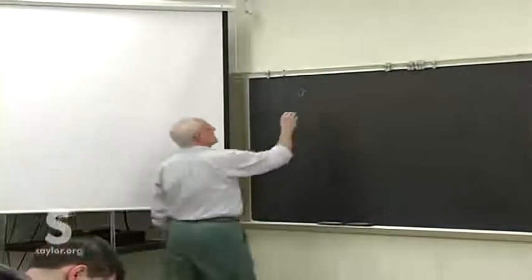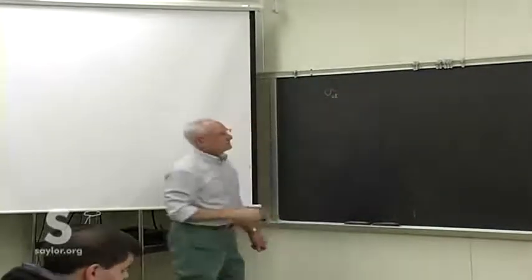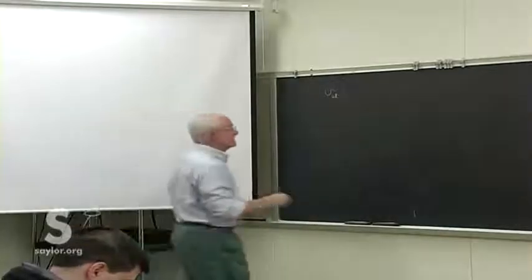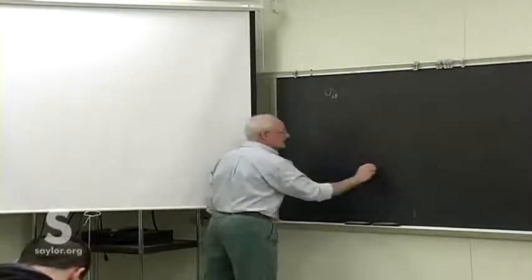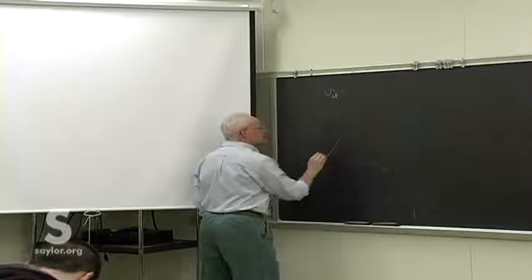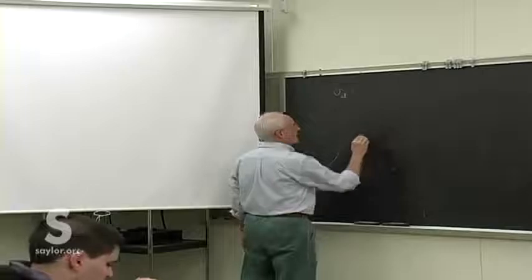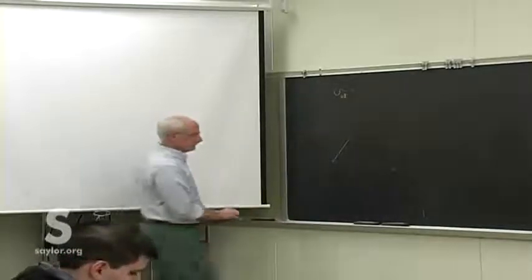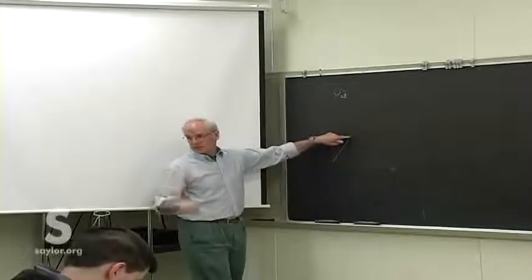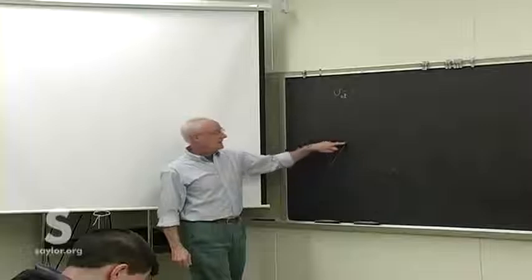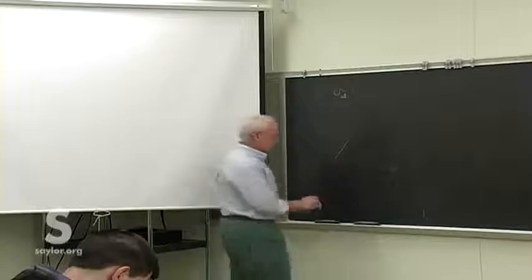The ultimate stress. The yield, is that the same thing? No. Well, it depends. If you remember when we looked at our stress strain diagrams, the yield stress is the end of the linear part. The ultimate stress is the highest it goes up to. Yeah, the yield stress is what you're worried about in structural materials, because when the load is released, you want the stress and the strain to be released too. Ultimate stress would be for other materials.